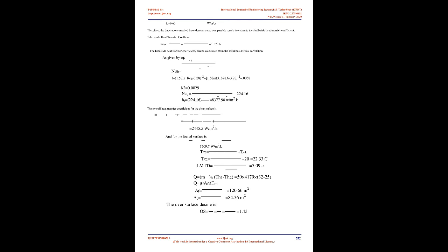The final design should meet process requirements, within the allowable error limits, at lowest cost. The lowest cost should include operation and maintenance costs and credit for ability to meet long-term process changes as well as installed, capital, cost. Exchangers should not be selected entirely on a lowest first cost basis, which frequently results in future penalties. 6. Basic design procedure of heat exchanger.